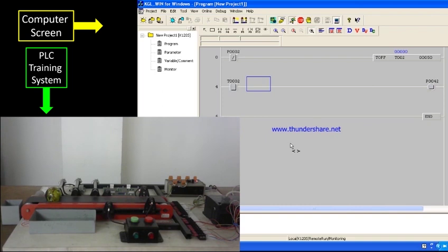So I am repeating this. If we keep our finger here or keep the item here in hanging position, look, the signal is not counting down. So we cannot have a continuous flow of input in such a scenario, in case of T off or timer off. We need to have a single pulse or a single press of input to have a perfect execution of the timer off.